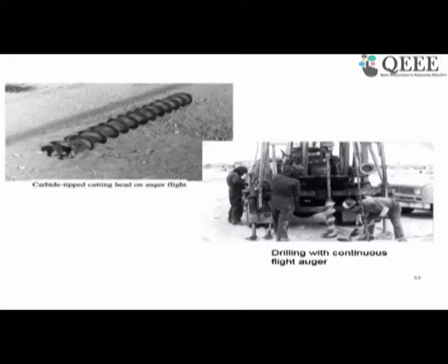So you can go to a deeper depth, but as you can see here, the soil will be highly disturbed, and just for classification purpose only you can use the soil, not for any testing.